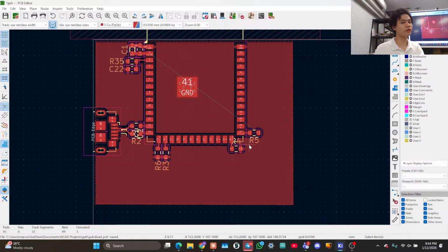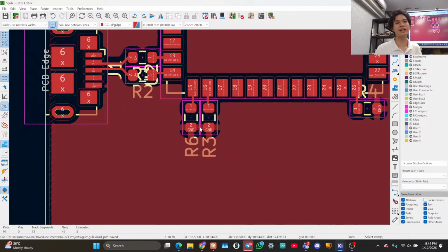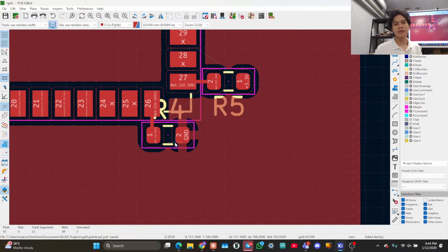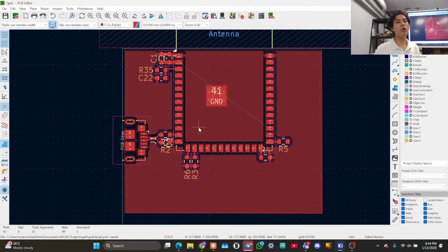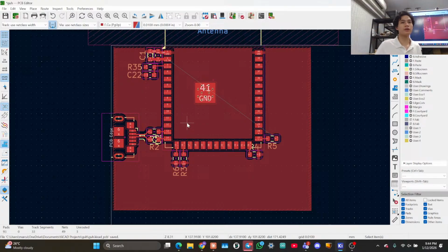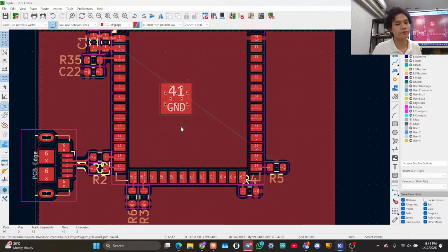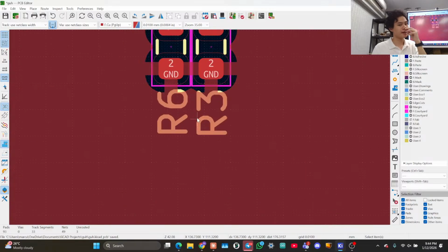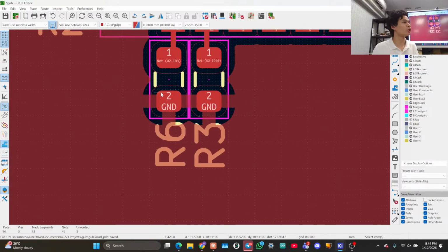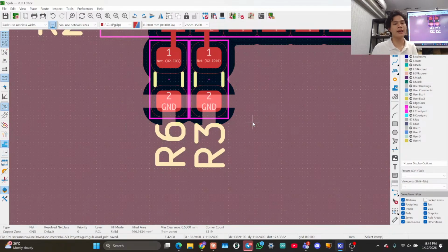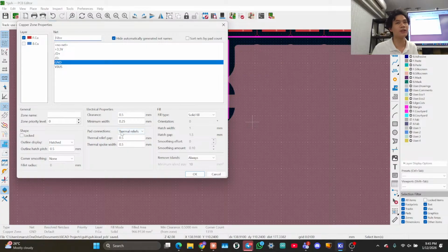This is an entire zone of copper, and check it out, it's wiring all the grounds together for me. This is called a copper pour, like I pour a liquid. It's connecting all of these grounds together, basically the widest possible trace we could theoretically fill the space with. And it's connecting with these spokes, which we call thermal relief. So it doesn't just fuse all the way, it connects with thermal relief on the pad connection.